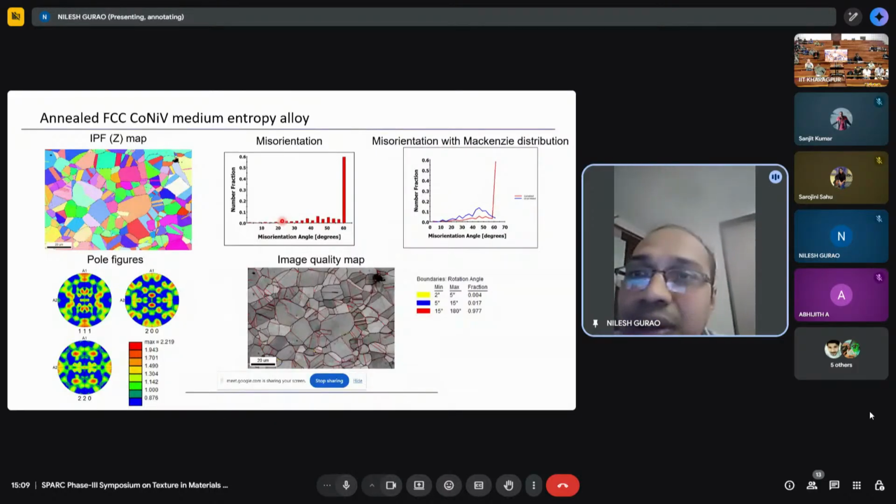Now, why 65 or 62.8, and why 90? The answer lies in crystallography. You should know why Mackenzie. What is the Mackenzie distribution? And why this boundary? Professor Sumantra Mandal must have talked about this. So, why are you getting these very high boundaries at 60 degree misorientation?